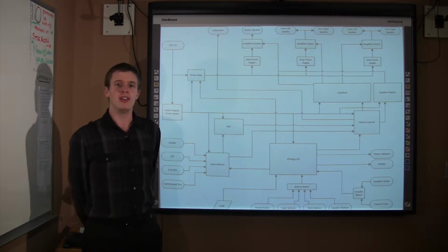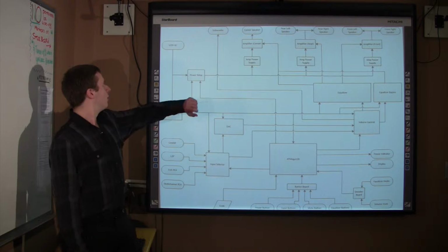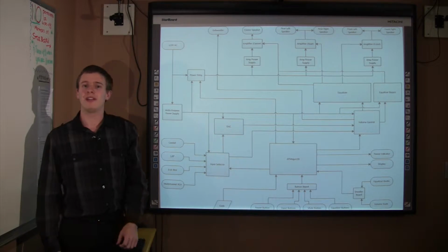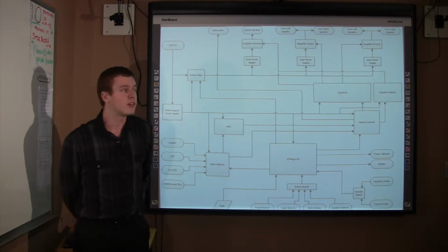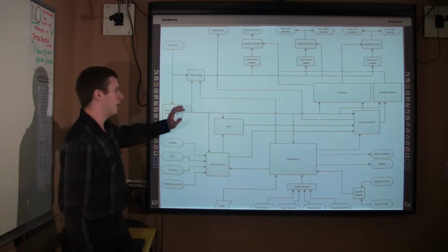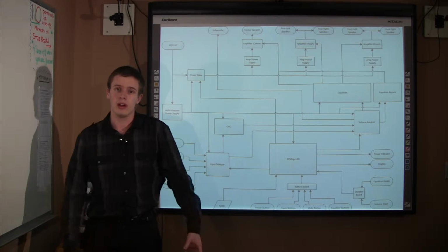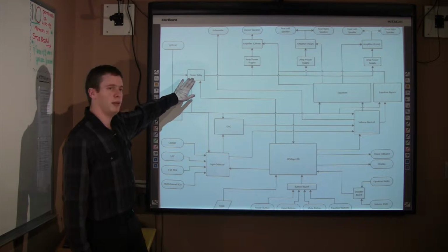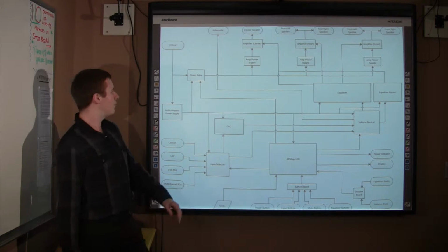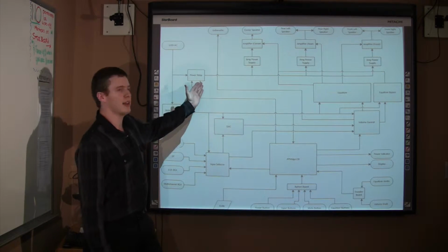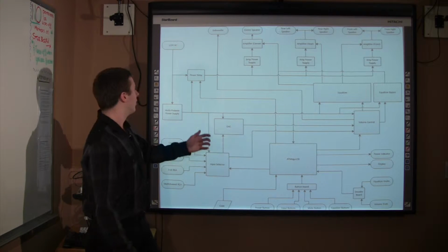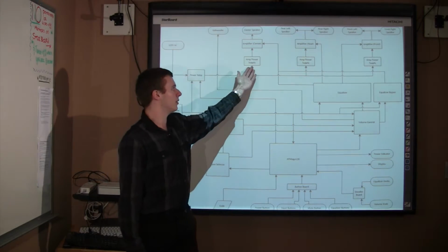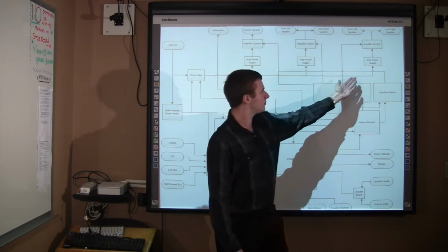To begin our detailed study of our block diagram, we will start with the 120 volts AC wall outlet. This is directly connected to two components of our audio amplifier system. The multi-purpose power supply, which powers various analog and digital elements, which Matt and Jesse will detail later, and the power relay. The power relay takes a digital signal input from the Atmega and, when enabled, forwards through the 120 volts AC through to our three amplifier power supplies.